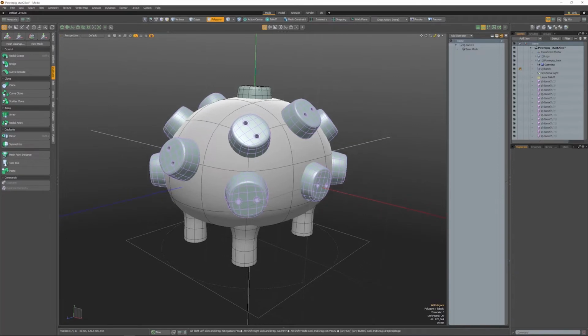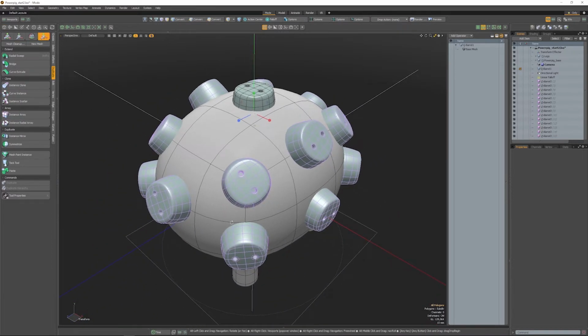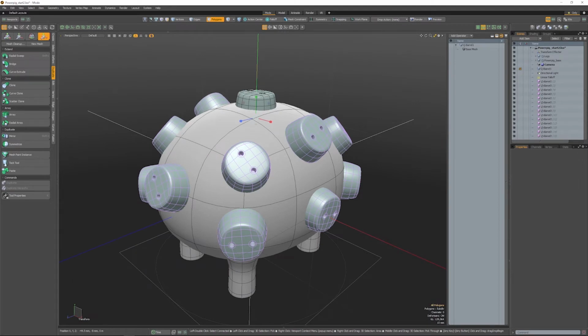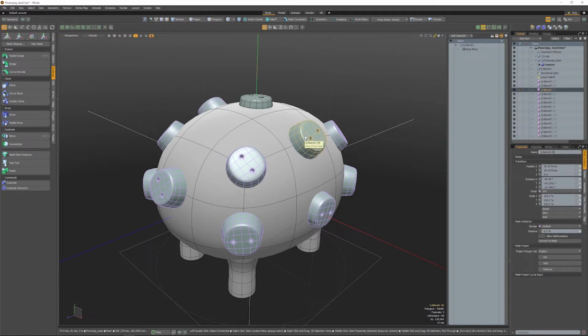But because they are all instances, if you select the one that they are instancing from and decide to move it, for example, everything changes. So one thing that I normally do sometimes, like scale, is really important, because it could be that, for example, here in the middle, you don't have enough space for the fillet. So if you make it a little bit smaller, then you get a little bit more margin, and everything will have more space for the fillets. You can still individually press W to move, Alt S to align it to the selection, or rotate it.